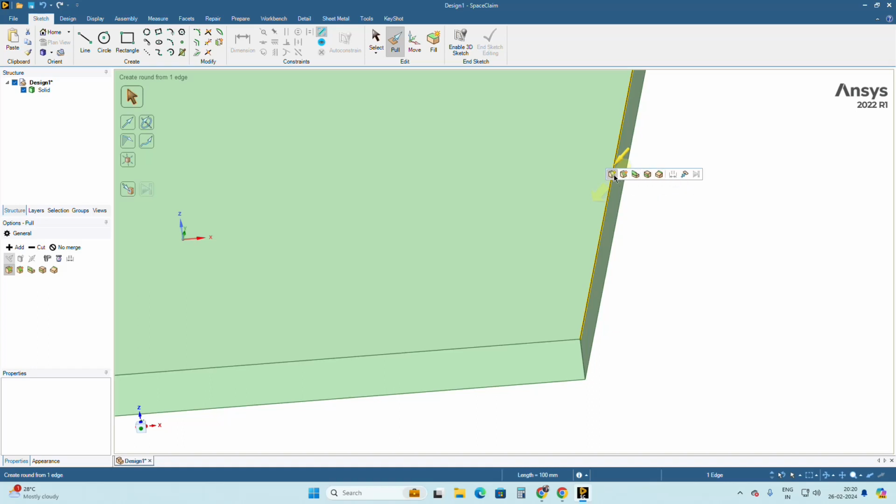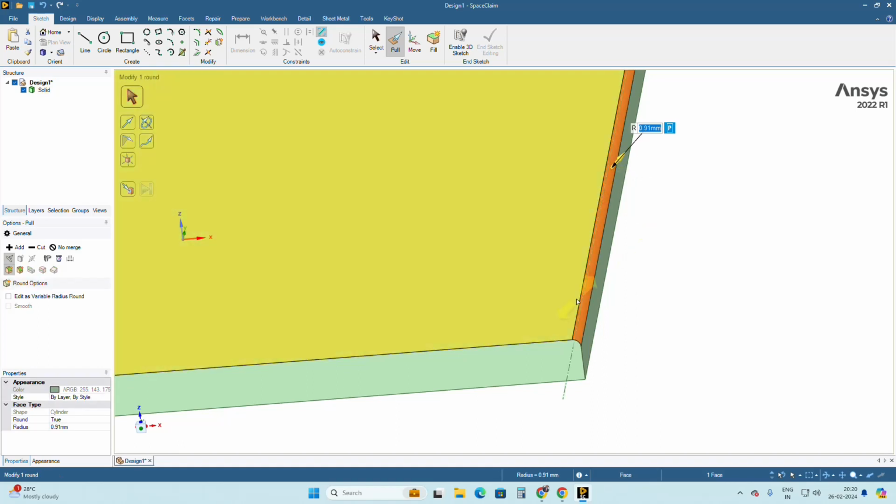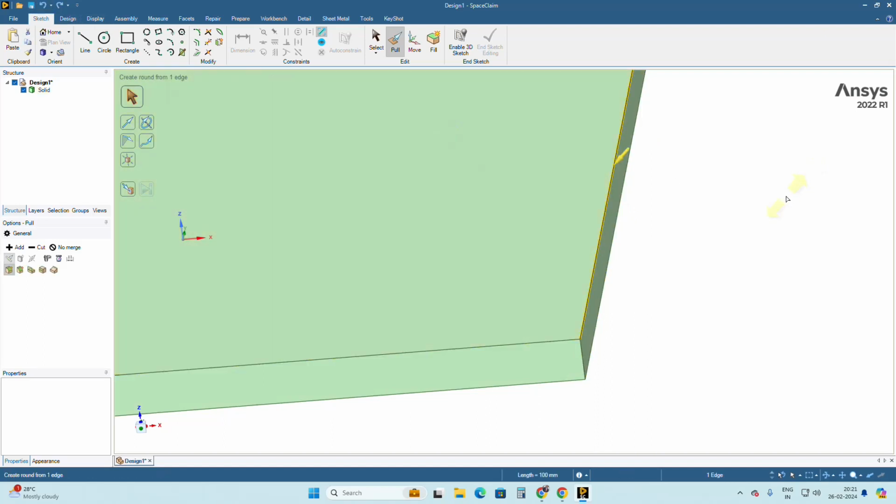Okay, if I want to chamfer this line, that is, I want to make rounded edges instead of sharp edges, I can do it by pulling up or down. By pulling up and down or by selecting the edges, you can give the dimension of the rounded edges. If you type a value like 1 mm or 0.5 mm and press enter, you get it. If you don't want to perform this, you simply press escape. Then if you click on undo, whatever you did will be gone.